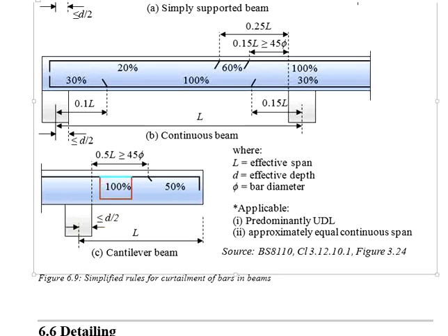You need to provide 100% reinforcement bar near to the support, within the regions at least half of the length of the cantilever beam, which should be at least greater than 45 times the effective depth. Only then you can reduce 50% of the reinforcement.